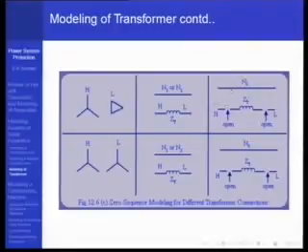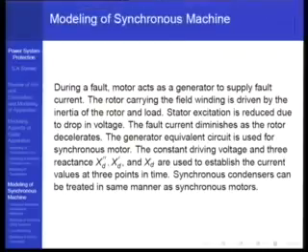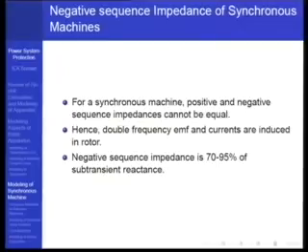Okay, synchronous machines, positive sequence reactance would be either of XD double dash, XD dash or XD. I mean, in the rough case, one of these three data will be used, depending upon when the fault strikes. Immediately after the fault it is XD double dash, after some time XD dash, subsequently in steady state it goes to XD. The synchronous condensers and motors also have positive sequence data that is in that sense similar.